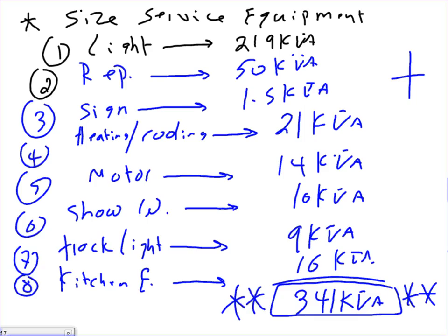Now you're going to ask me what type of voltage system you want. We were working with 208/120, so we might as well continue with 208/120. By the way, at this point you can change your mind and make the system 480/277. But then you need transformers downstream. It makes sense to continue with 208/120.